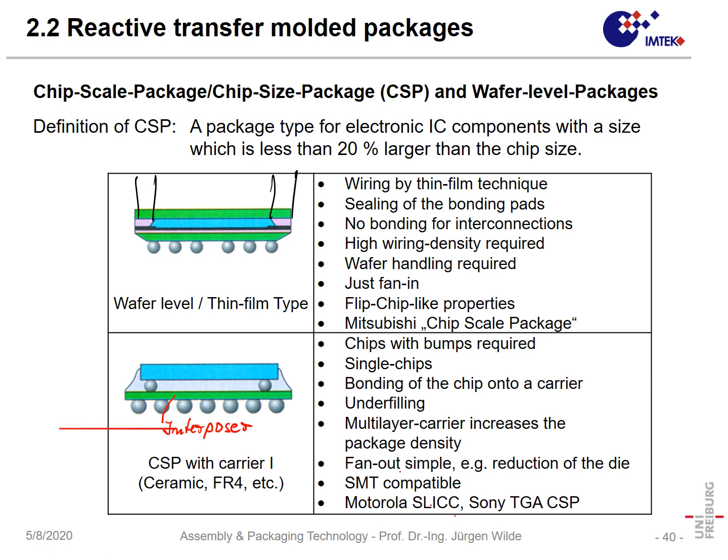Okay, I would say that device is in limited use, and a completely different design was something where we had a complete wafer, and the complete processing is made on the wafer. Here we have the silicon. The silicon wafer is mounted on a polymer. Then we can etch trenches in the silicon. We can put on a front side polymer.